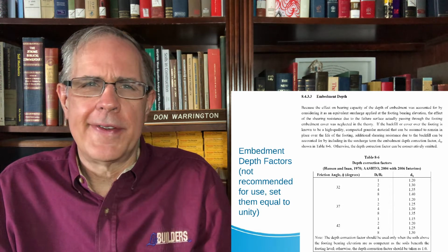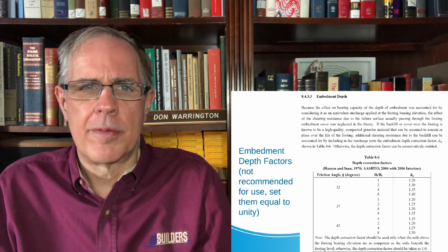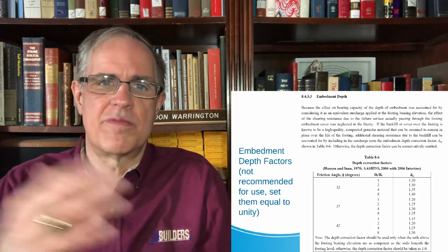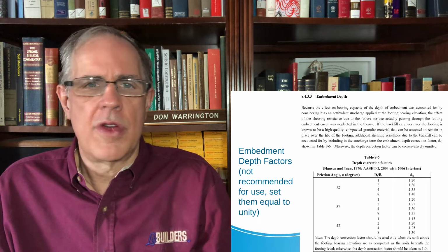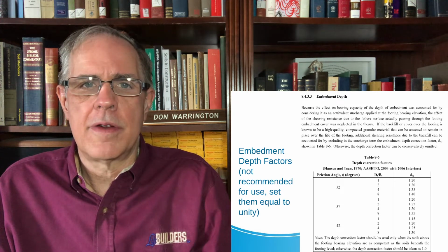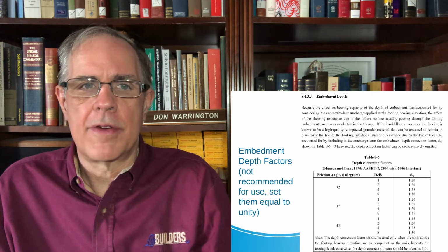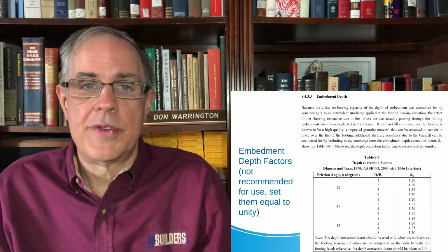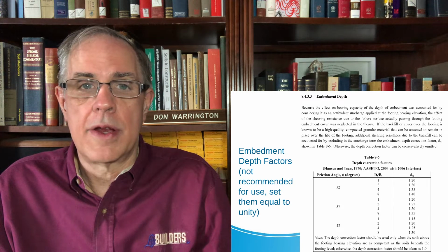Because fill is an unreliable thing in terms of its consistency, particularly if they're just covering up whatever it is, don't do this. And I see this every time I give this. Students will dig into the embedment depth factors and try to use them. There's no sense in having them. Do not include them in the calculations.